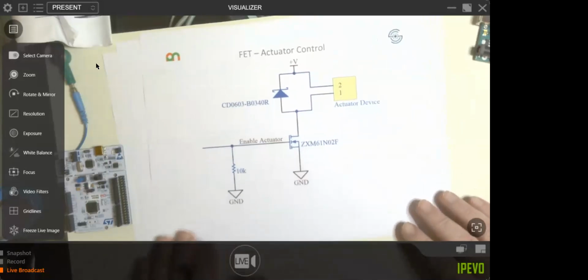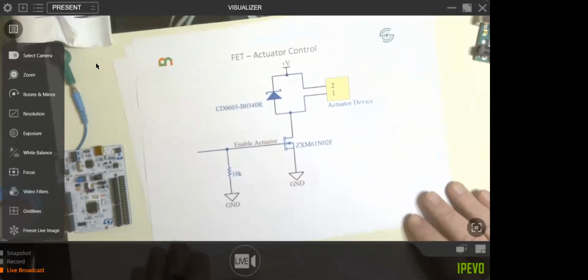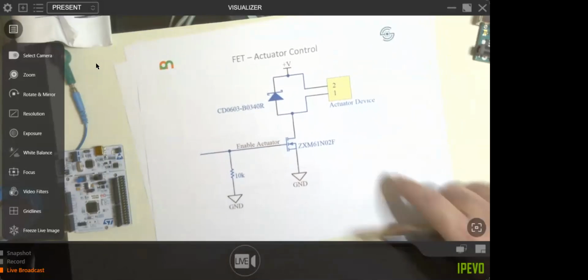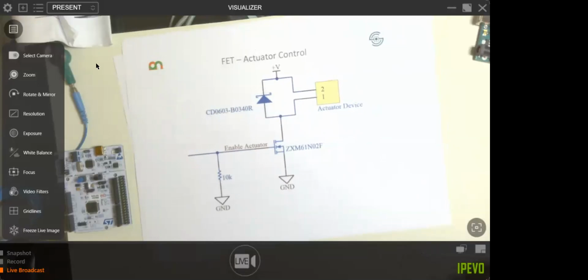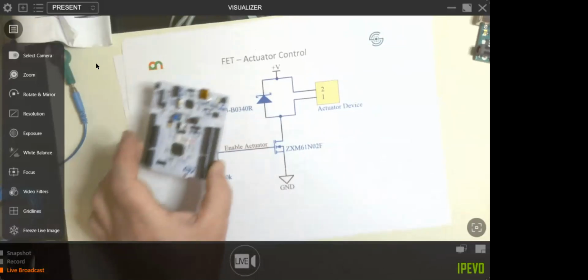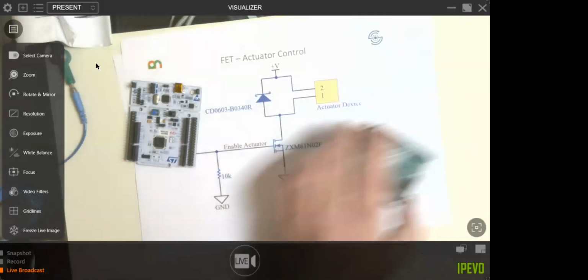Right, the other thing to use transistors for is controlling. It says actuator here. By an actuator, we mean something like a motor or a haptic motor. We'll talk about them in a second, actually. So if you've got little buzzy motors, the sort of motor you have for vibrates in your mobile phone, they can draw quite a bit of current, certainly to start. And they'll probably draw more current than any of these microcontrollers can deliver.